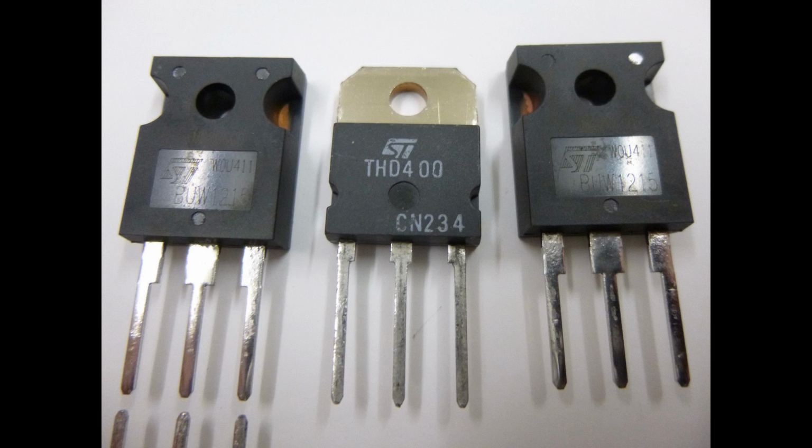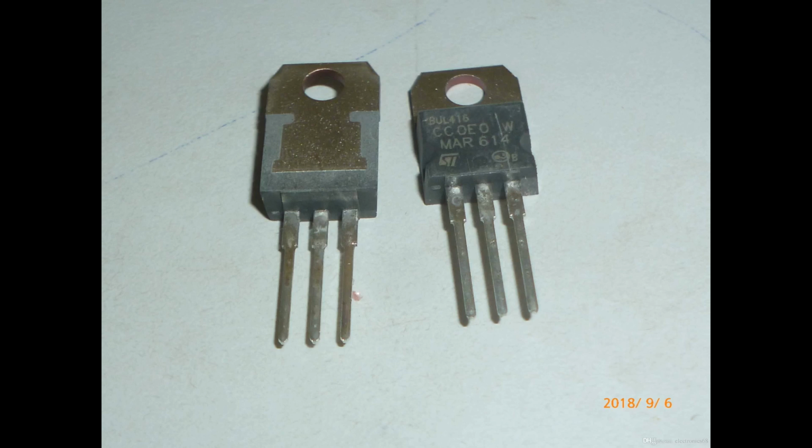received AM signal. Frequency modulation, FM, involves varying the frequency of the carrier signal in proportion to the information signal. Voltage-controlled oscillators, VCOs, with transistors are commonly used in FM modulation circuits. Transmitter. The VCO, controlled by the information signal, generates an FM signal by varying the carrier's frequency. This FM signal is then transmitted. Receiver. In the receiver, transistors are employed to demodulate the FM signal and retrieve the original information signal.